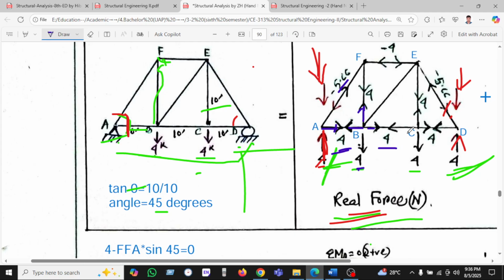So in the same case, similarly we can use it for joint C. We can see the joint B is going rightward is 4, so preventing this force it will also go right. As in symmetric cases we can use the same value. As we know that this 4 is upward, so it will prevent also downward. So that's why I'm drawing the symbol downward is 5.66.